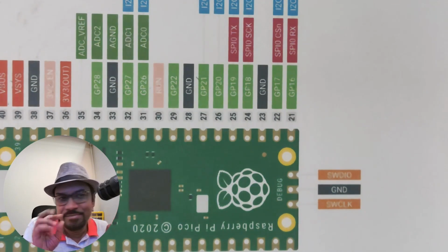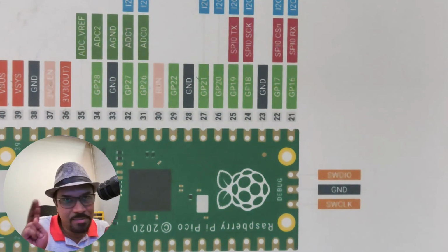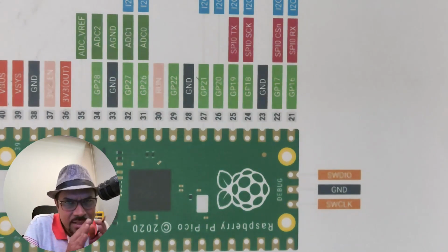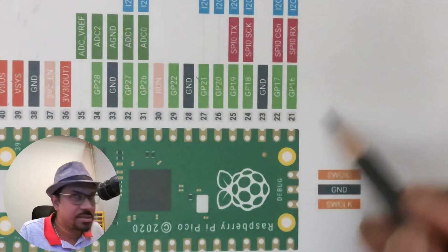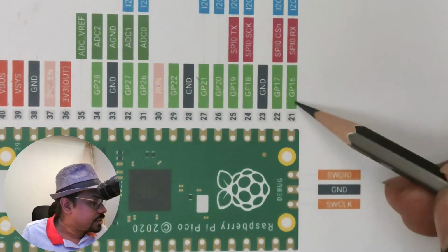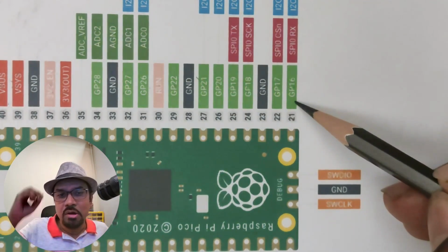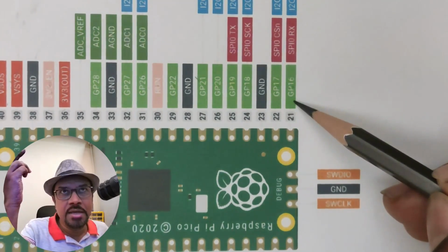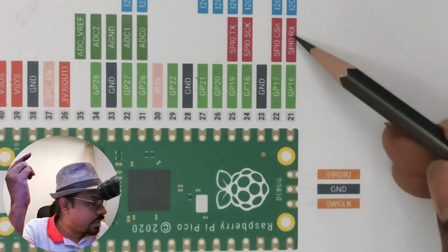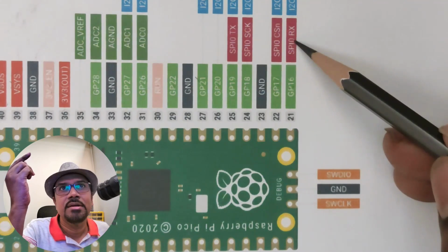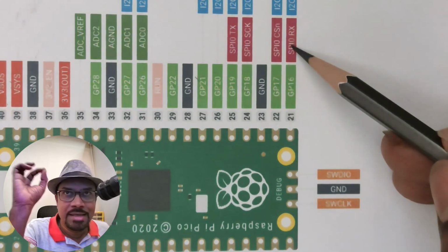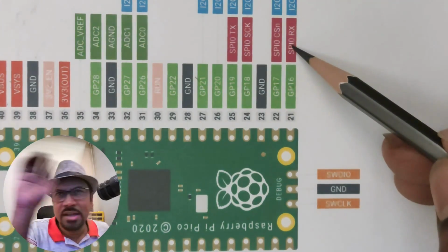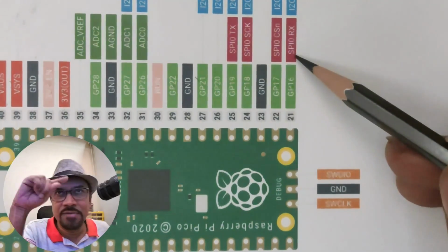There are 2 pins for supply, which is VDD and ground. And there are 5 more pins. And those 5 more pins are connected through this side, right? So if you see this particular GP16, you can configure this as an SPI interface because you can also see an SPI RX, right? I'm connecting the reset onto this particular pin. Reset can be connected anywhere, but I'm just choosing this for the convenience.